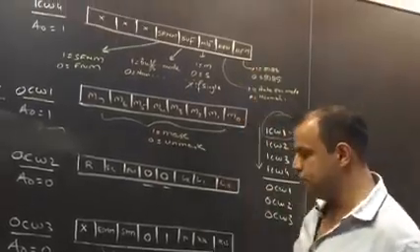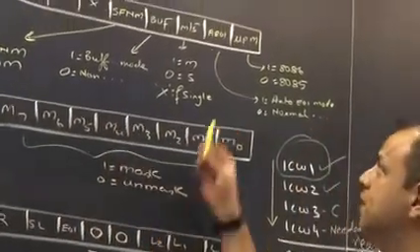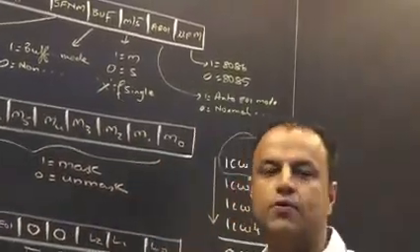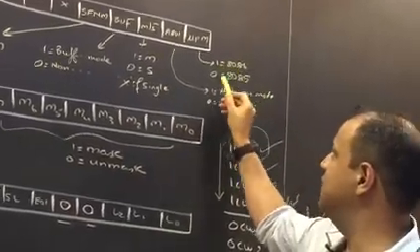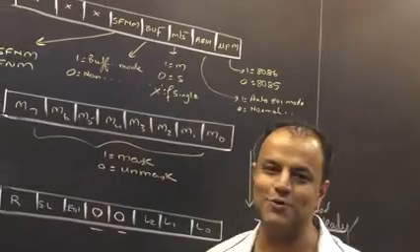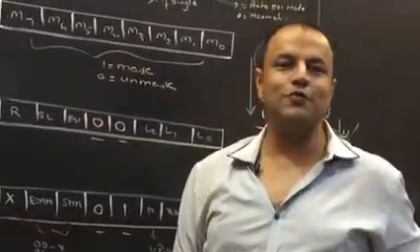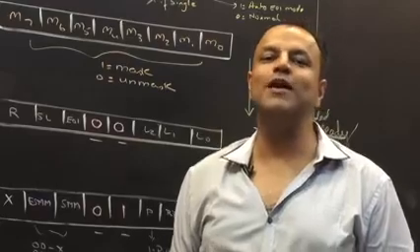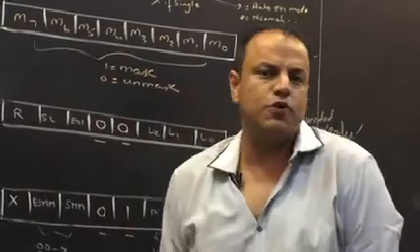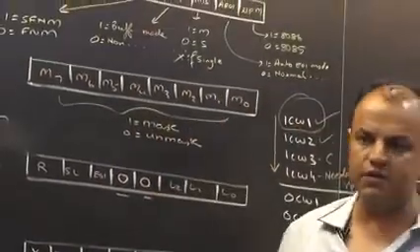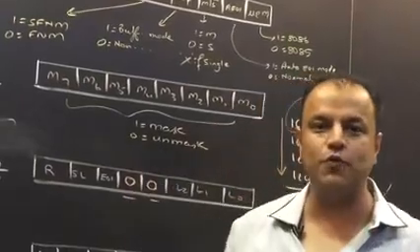The first bit over here is the MPU mode, M, that means MPU mode. So you're telling who your MPU is, whether your MPU is 8085 or 8086. 1 means 8086, 0 means 8085. What did you immediately understand? If you don't give ICW4, 8259 will work like it's working with 8085. So for 8085 programmers, ICW4 is optional. If we need the other features, we'll give it. Otherwise, we don't give it, it's fine. For 8086 programmers, ICW4 is a compulsory command.